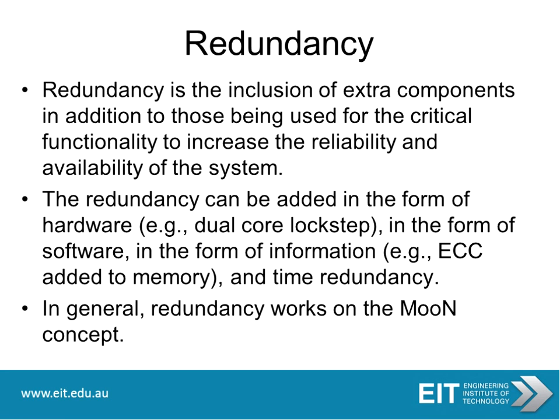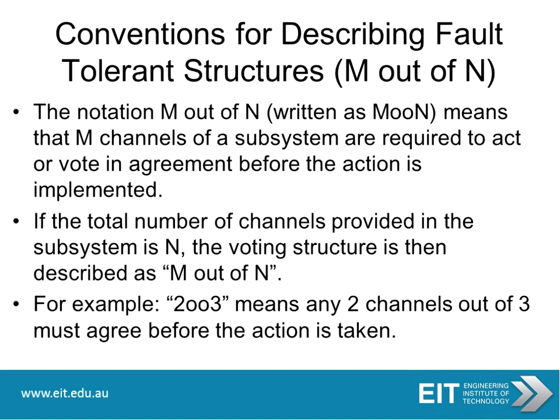Redundancy is the inclusion of extra components in addition to those being used for the critical functionality to increase the reliability and the availability of the system. And redundancy can be added in the form of hardware, for example, the dual-core lock steps, in the form of software, in the form of information, and time redundancy. So in general, redundancy works on the M out of N concept.